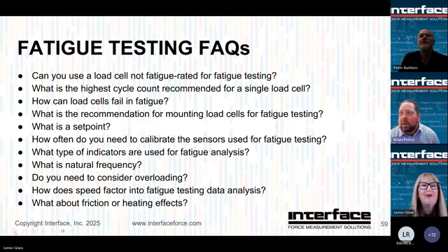Okay. If I heard the details correctly, as long as you complete a test within a year, I would recommend, until you start having good data, to have the load cell calibrated annually. Now, if you do that and the load cell still looks good, no change in performance, then maybe you can extend that interval out. We have some standards that we use for calibration that we don't have calibrated every year or every 2 years even, because we have 40 years of history. So again, there was a lot in there. I'll take a look at it if it's posted, and we'll get back to you if I have any more specifics on that. But it's going to be kind of your call.